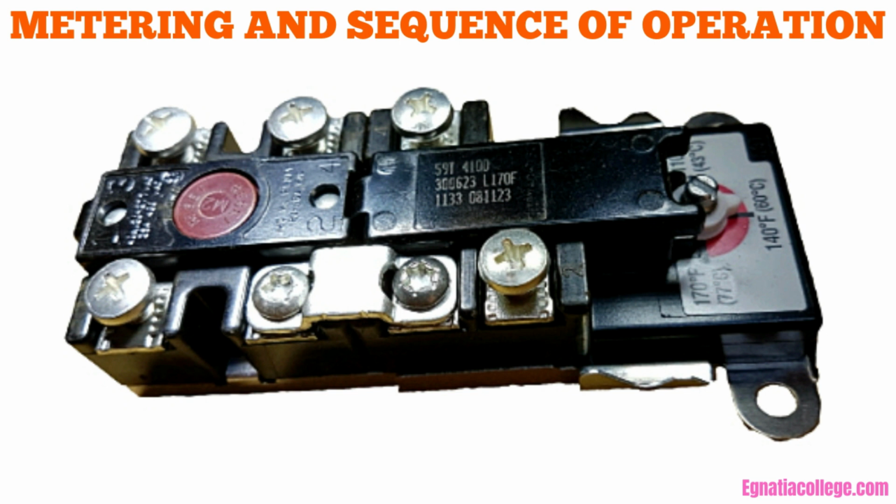This wire is connected to a separate terminal block located at the 3 o'clock or 9 o'clock position in the meter base. The electrician then connects 2 red number 10 AWG solid wires to the terminal block at the 3 o'clock position and to the water heater lug on the line side of the meter base. These wires pass through the service conduit and through the main disconnect into a separate 30-ampere, fusible disconnect. The number 10 wire, AC90 or NMD90, then connects to the water heater.